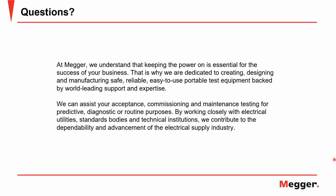So that is when symmetrical components, positive sequence and negative sequence, especially for three-phase faults, come in. Positive sequence directional elements would be much more accurate and reliable in that case when compared to the protections that electromechanical relays could do. Luckily, three-phase faults are not so common.